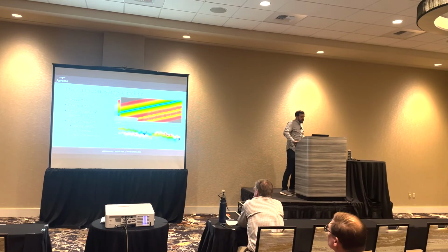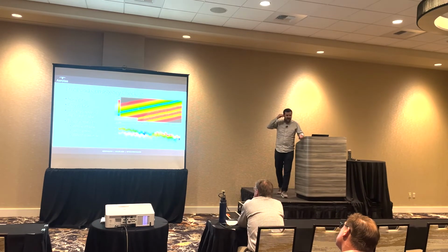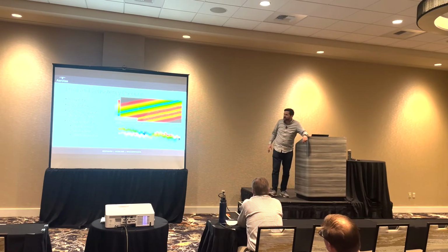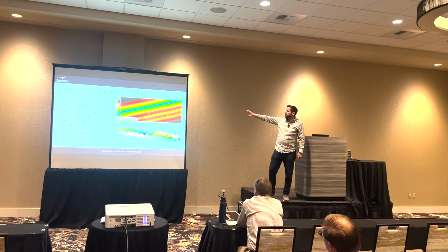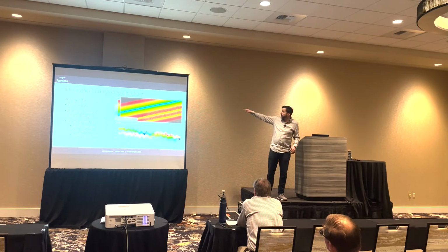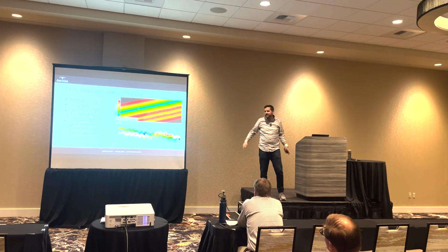This is another interesting error that we've been researching exactly how to properly mitigate. This is one where high scan angles can cause erroneous data. I need to explain this because it's second nature to me, but probably not an intuitive image to a lot of people. At the top, what you are seeing is the LiDAR point cloud classified by scan angle. That means the angle from the drone to the actual ground. The blue line is effectively the flight path of the drone. It flew along there, and blue is where it is pointing directly down. Everything else is the scan angle. The LiDAR is scanning sideways at an angle, so it's a little bit higher.